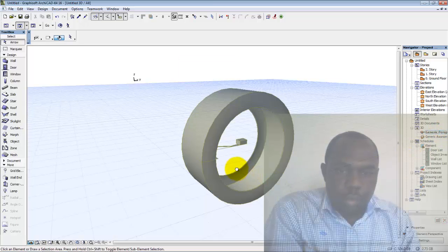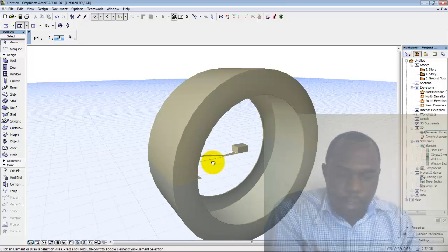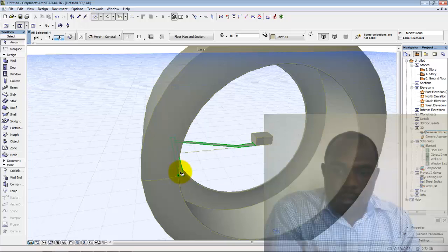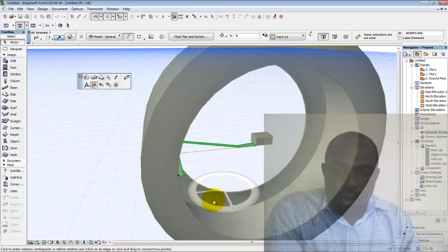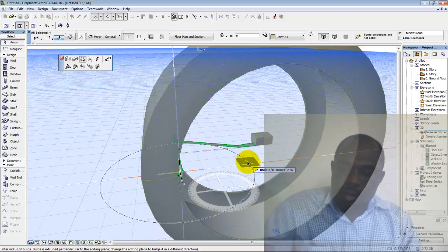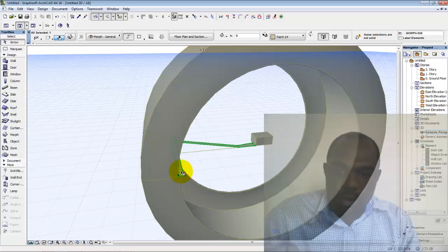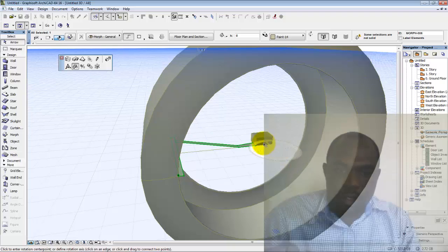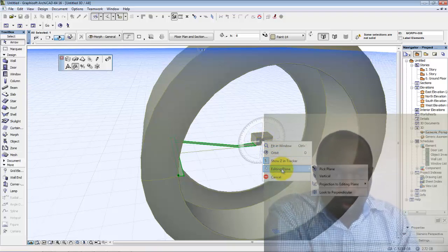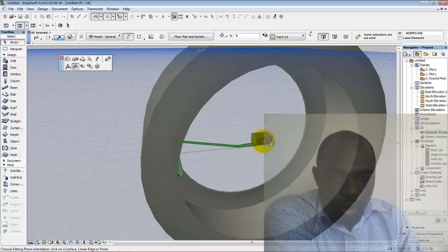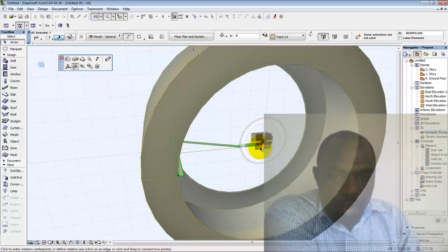So go to this part, you can see that's the section for it. So we can click here. Even in the section view, it's on free rotate. Just press escape, click it again, the surface, not the line. Make sure free rotate is selected. Then you right click, don't left click yet, right click, then select pick plane, and you click on the surface of the box that we're using as reference.